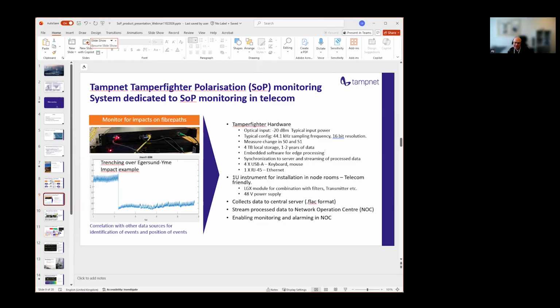Because if you want to do real-time streaming of data and representation, then you would like a compressed data stream, which more shows the changes, like the one I showed you in the cat video. And the raw data we synchronize to a server, and it's all built on a Raspberry Pi. So we have keyboard, mouse, and display, and we have Ethernet through RJ45.